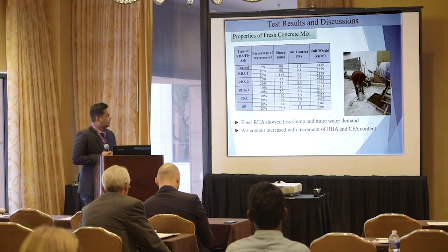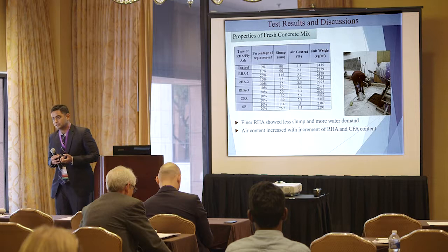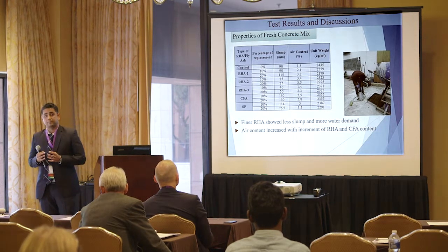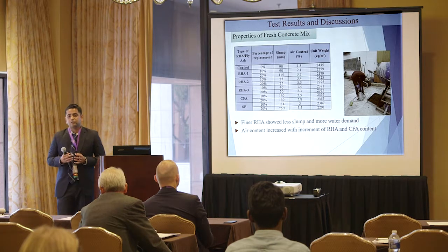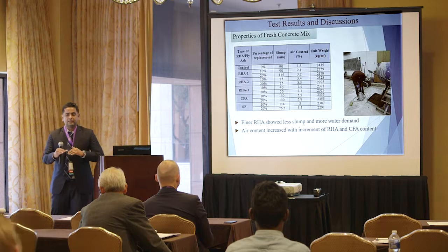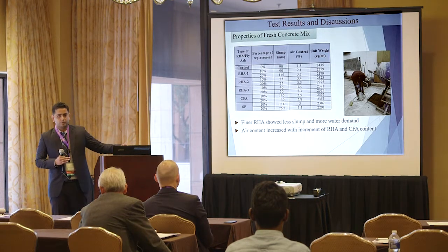Because of the finer materials, the concrete mix gets stiffer, so it needs more water to have the same consistency as the control sample.